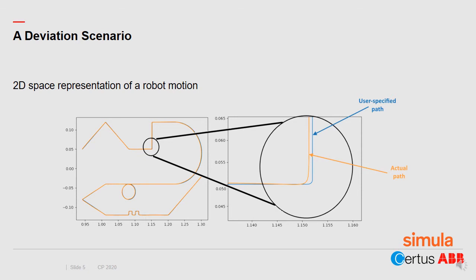During the execution of this test, the robot is following this program. But you can find a small deviation between the specified trajectories and the actual trajectories performed by the robot. So the goal of RobTest is to create the test program that can be run on the robot and to detect the deviation between the specified trajectories and the executed trajectories.